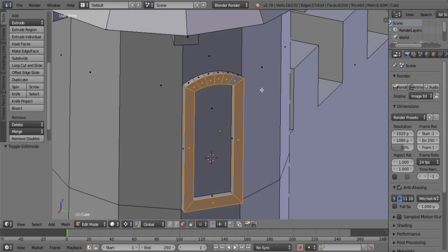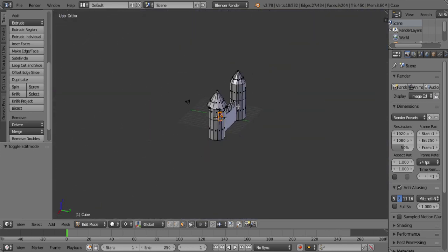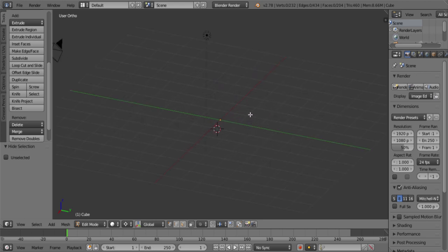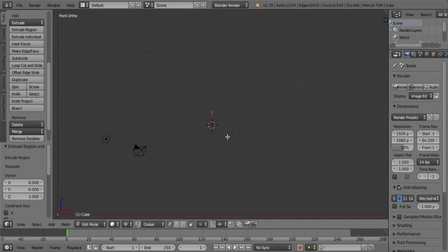Now with regard to proportional editing, I'm going to veer off a bit. I'm just going to hide this, select all, hide. I'm going to design a car wheel. So I'm just going to create a new vertex, front view, snap selection to grid, snap cursor selected, and I'm going to extrude, extrude, extrude, because a car wheel is a perfect example to show some proportional editing.